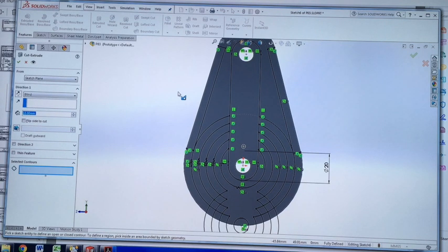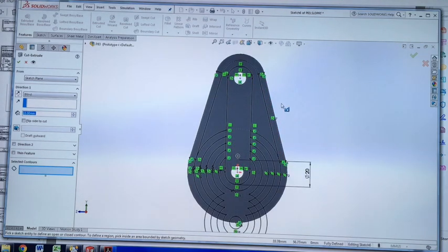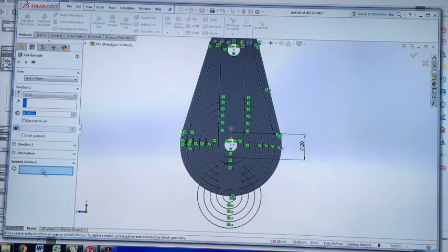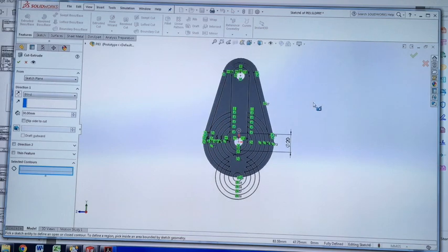If you can't be bothered creating enclosed shapes, basically outlining every single part that you want to cut away, you can half create it, and then when you do your cut extrude, it'll ask you to select contours. In this case, all I have to do is select the areas that I want to remove. The shapes that I've cut will give me some options, and then I say, I want to cut away these areas.